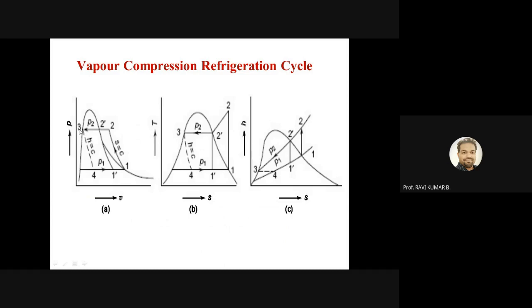If it is a 100% effective condenser, with effectiveness 100%, we can get this stage, which is called the liquid. But if it is ineffective, maybe 90% efficiency, in that case we will not be able to reach here, and some additional cooling is required to ascertain that the entry to the expander should be a liquid. Now, once we reach 3, the process starts, an expansion in the expander.